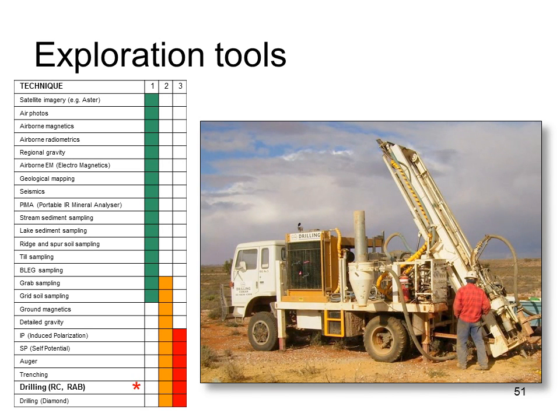Another drill method that you'll hear about, and is particularly common in Australia, is RAB, or rotary air blast. It's very similar to RC, but it doesn't have the double tubes in the rods, so the sample blows up the outside. Advantages? Well, it's very quick and cheap. The disadvantages? It produces chips only, like the RC.